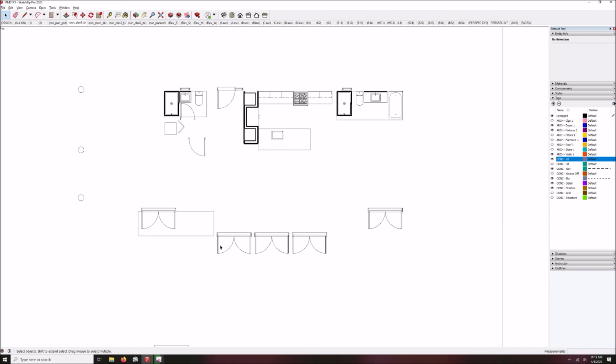And what you're seeing here is what will become eventually a floor plan with, here are the doors, showing the door swings. And those are the 2D parts of the component. I've also got fixtures showing up here. And I've got these heavy lines, which are not walls, they're actually the finished panels that are put onto the walls. So everything you see here is going to eventually go into my construction drawings in the form of thin lines.